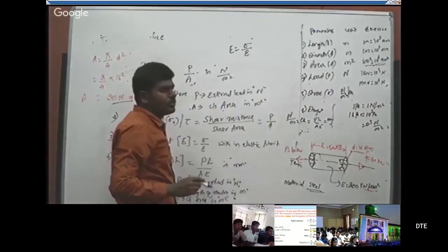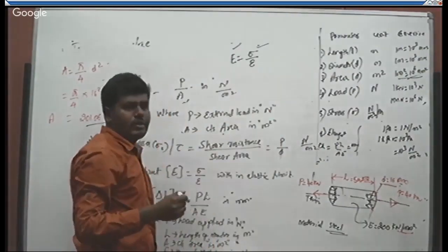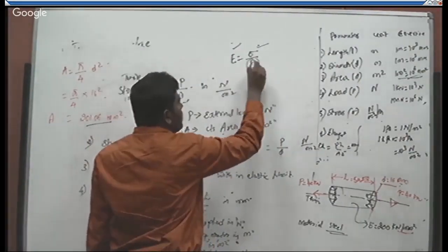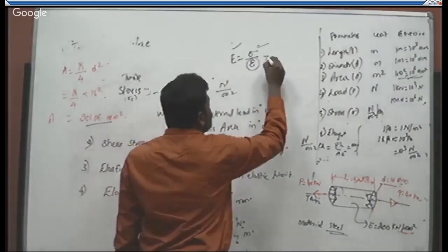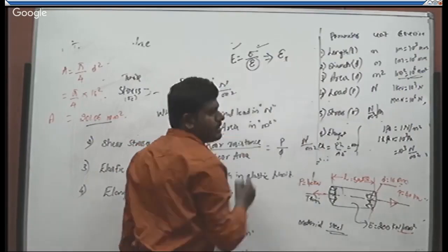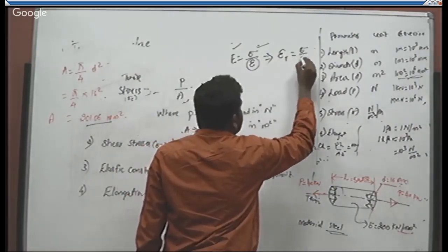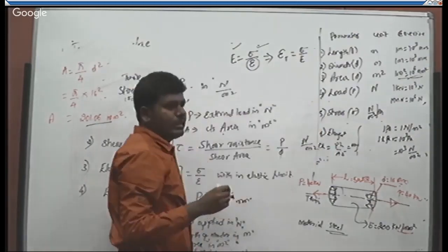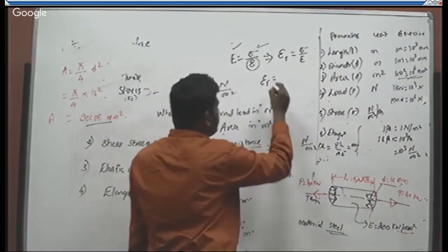Okay, so we have a stress value and we have an elastic modulus value. The only parameter left unknown is strain, so we can rewrite this formula for strain. In this case, the tensile strain due to the action of tensile loads is given by sigma by E, the ratio of stress to elastic modulus. So substitute these values in this particular expression.